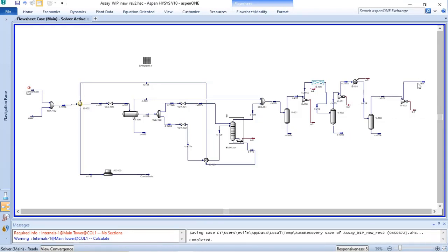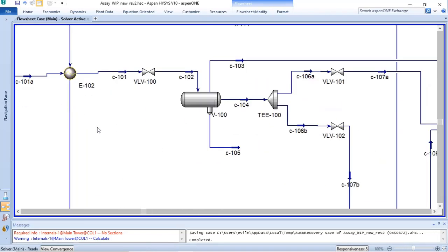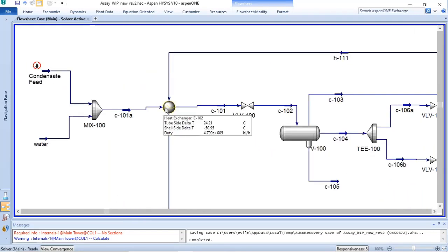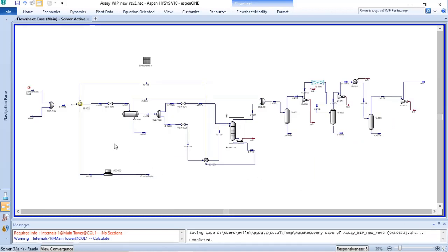and in the final stage it was not considered after cooler, and he asked me to verify why the heat exchanger, this one E102, was not converging. And the first thing that I can tell you is that the Aspen HYSYS or chemical process simulation sometimes accept everything that you tell him, and you need to have a critical evaluation of your process simulation to verify that it is feasible, if it makes sense.